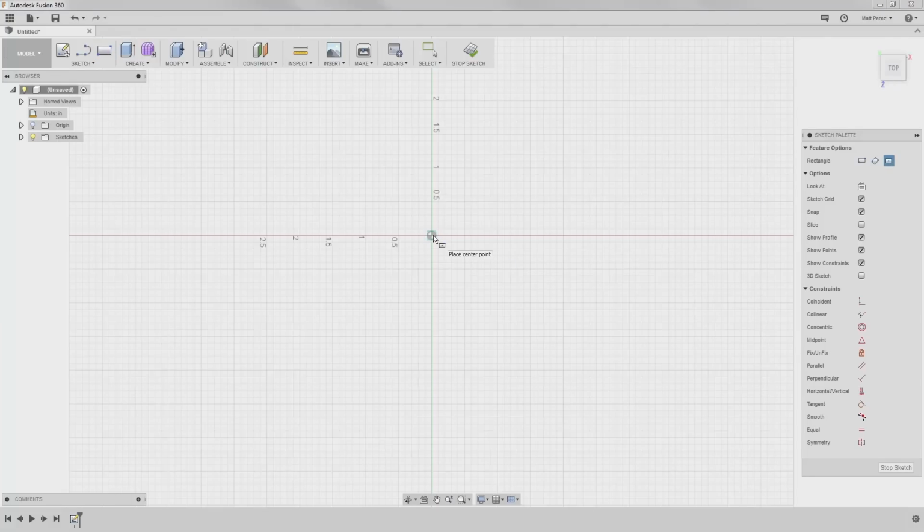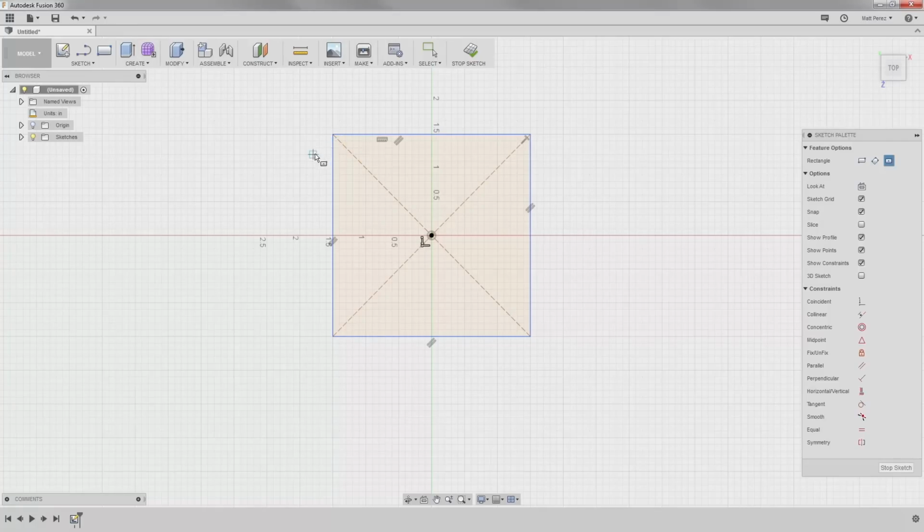We're going to left click at the origin and drag this out until the dimensions are roughly 3 by 3. Now you'll notice that the bottom dimension is highlighted and it snaps to various options based on our grid settings. So you want to go to a 3 by 3 and left click. Notice that I didn't place any manual dimensions in the dimension boxes. I simply dragged the rectangle out until it was 3 by 3. Because I didn't manually place any dimensions, the dimension values have disappeared. And that's okay because right now we're not focusing on placing dimensions.